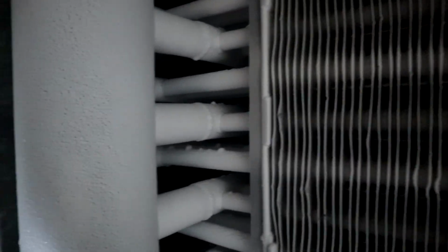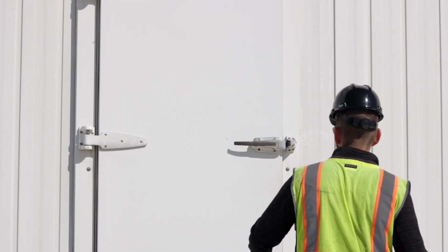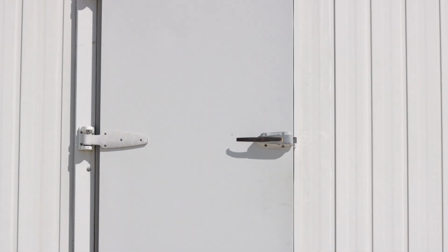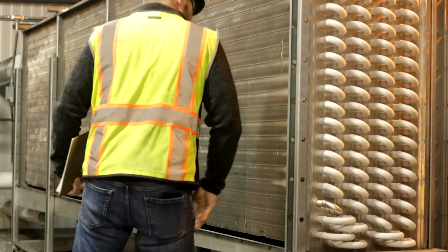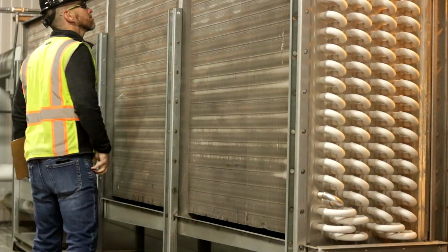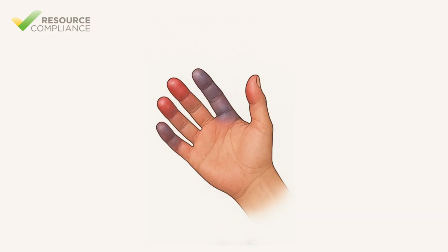Treat it as a warning sign. Address the root cause as well as the immediate hazard to maintain both safety and system reliability. Working in and around refrigeration equipment exposes technicians to extremely low temperatures from both the environment and the refrigerants themselves. This creates a risk of frostbite, a cold-related injury that can cause permanent tissue damage. Frostbite can occur through direct contact with cold surfaces or prolonged exposure to cold environments without the proper clothing.